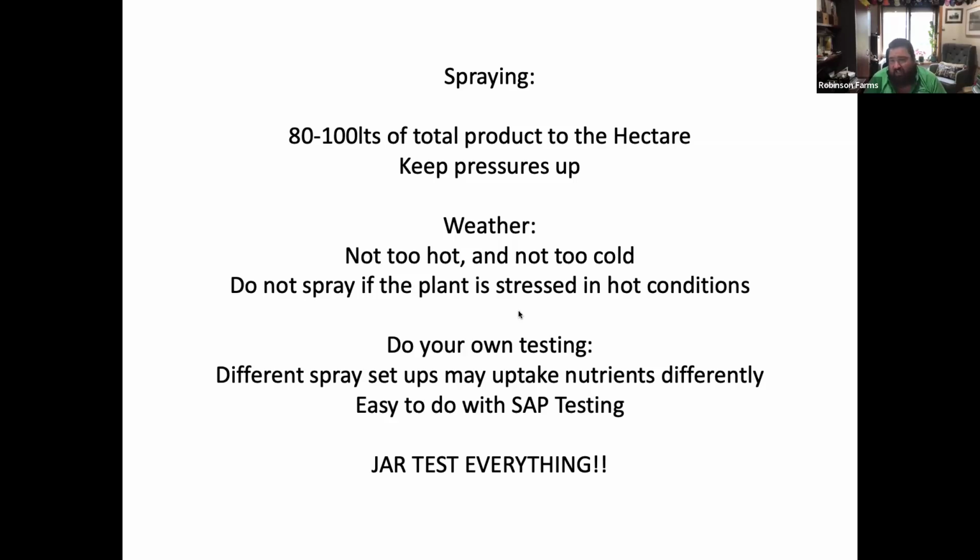And jar test everything. If we're going to add something to the boom spray, don't just guess that it's going to be okay. We've made two or three, lots of, well, not jelly, but products that have either fallen out of suspension by adding something in that we didn't realize wouldn't behave. But sometimes there's a way around it.